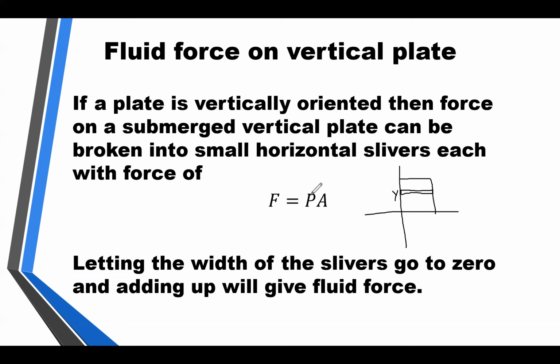Well, pressure is going to depend on weight density multiplied times the depth, so wherever the water line is, down to y. And then the area, well, each of these slivers is going to have some sort of a length. Obviously I drew a square, but the length times width is going to give me my area of each of these little slivers.